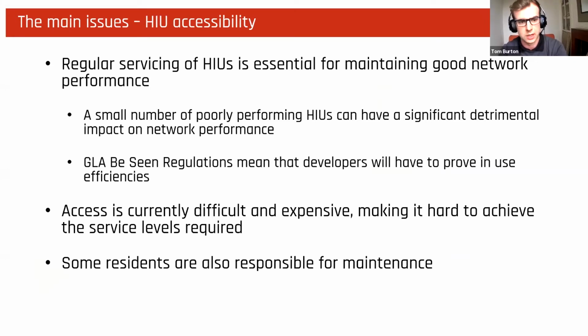This really boils down to the fact that to maintain performance from handover throughout your network lifetime, you need to be regularly servicing HIUs, and this can't just be most HIUs. It really has to be 100%, because a very small number of poorly performing HIUs can have quite a significant impact on network performance.